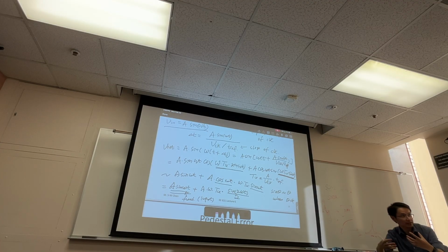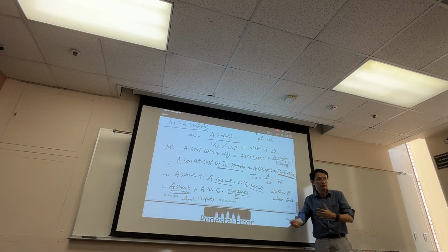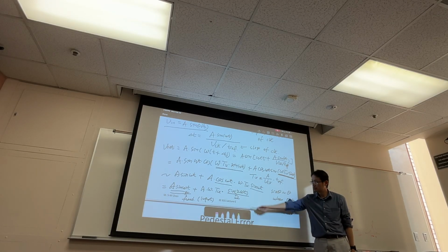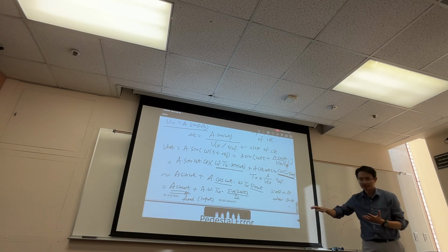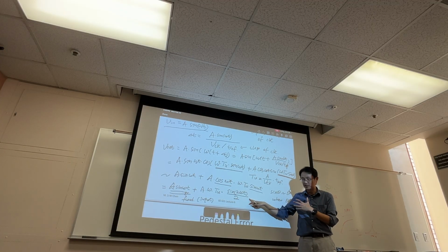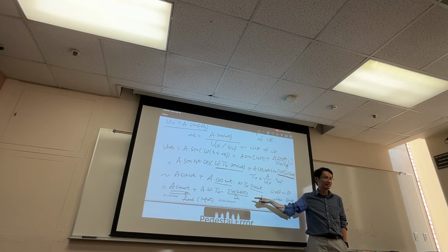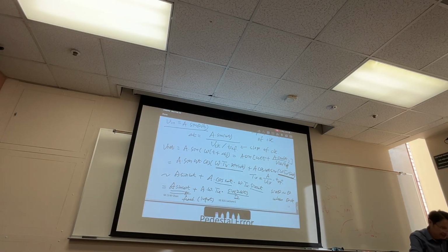On the spectrum, assuming this track and hold is going to be used by the ADC, and at the output you do FFT, what do I see? What is this? Noise floor or distortion? It's harmonic distortion. Not only do I know this harmonic distortion, I know exactly which harmonic. Which harmonic is this? Second harmonic. Right, this is what we call the second harmonic, because you have a 2 omega t.